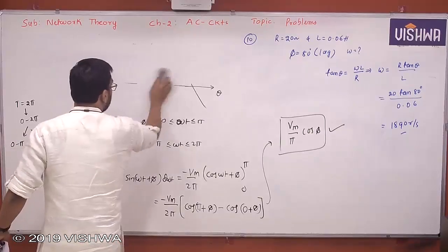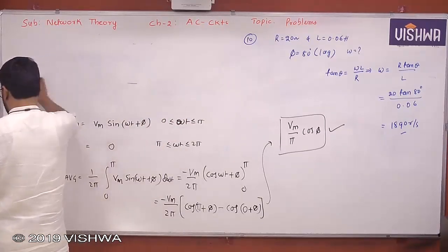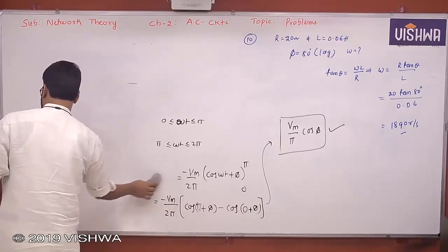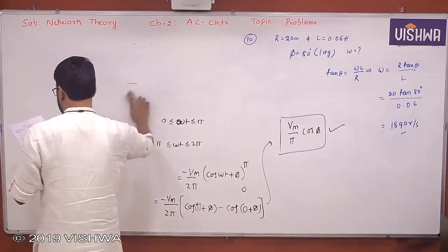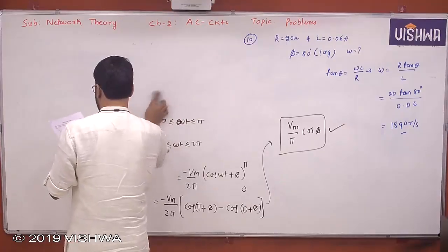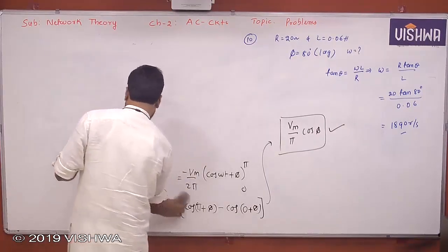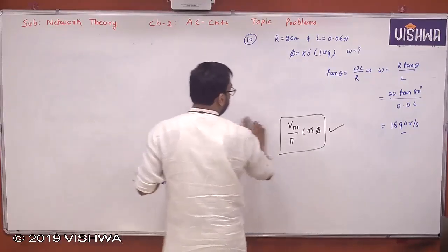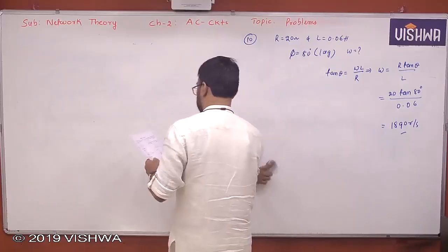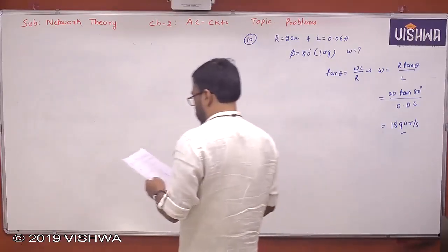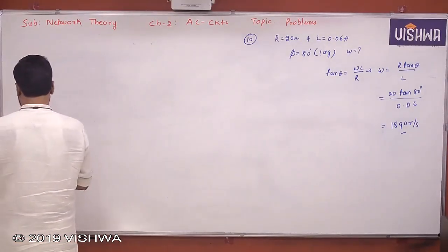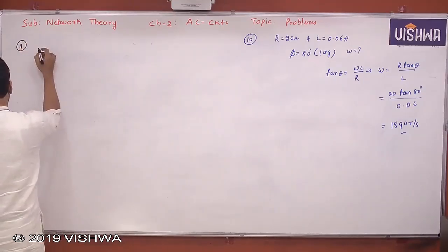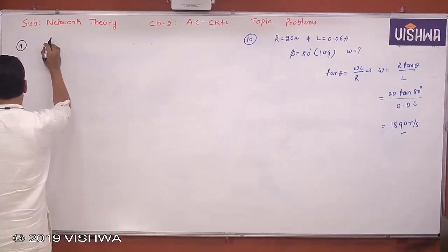Note down that quickly. 11th problem. What is the 11th problem? A series RL circuit has L is equal to 0.02 Henry and an impedance of 17.85 ohm. The current lags the voltage by 63.4. 11th problem, classroom workbook. Calculate omega and R values.